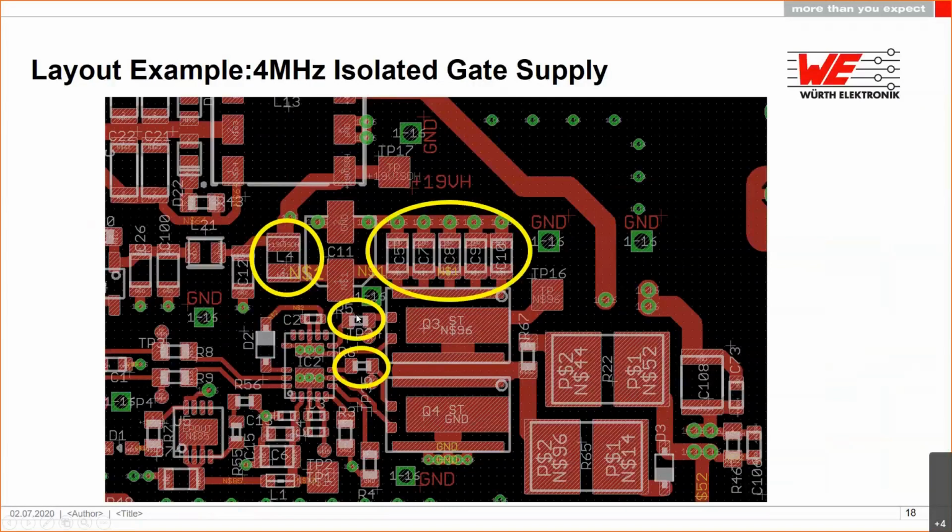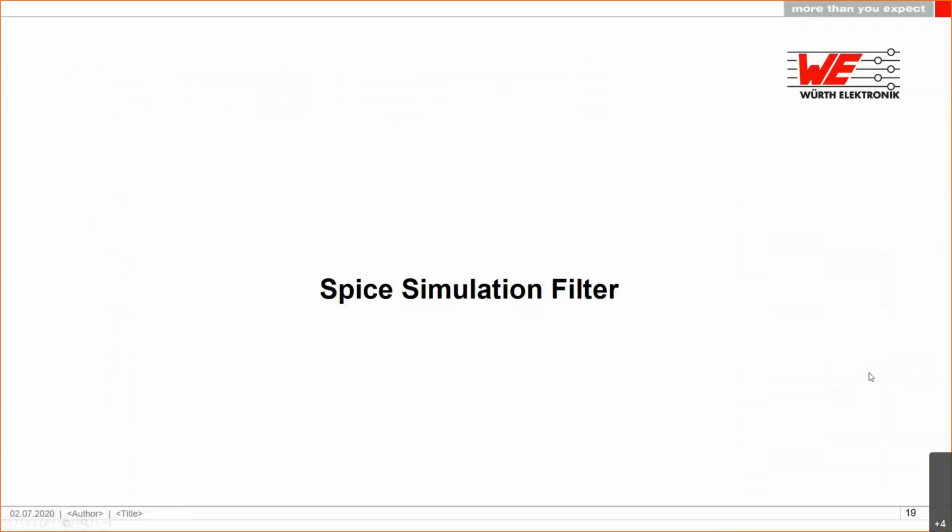As I said, these are the GaN resistors that turn on and turn off from the low side. And we have here the filter for the GaN drive with respect to the VCC, the plus 19 volts. And of course, we have a higher power loss due to the high switching frequency and the high currents here. For the gate drive resistors for the SiC FETs, we need at least 2 or 3 watt types, so they are a little bit bigger.